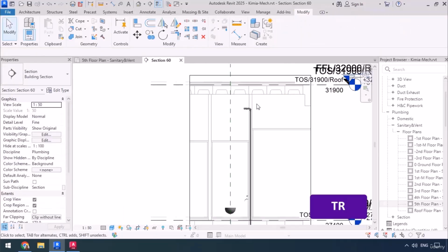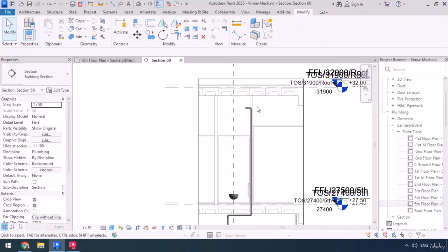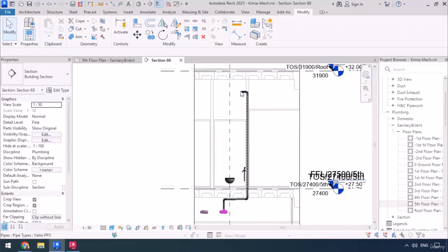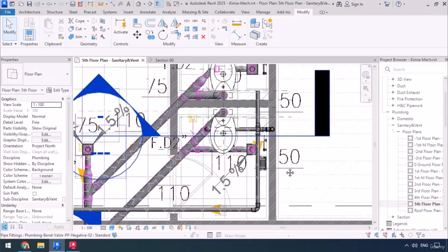So that's why I said that it's best that you start with the lavatory pipes, and by drawing the lavatory's vent pipes, we understood that if we have sanitary pipes down here, then the vent pipes are going to have to be up here. The sanitary pipes were for lavatories, as well as the toilet fixtures. For the lavatories, it was clear enough that the vent pipes need to go up, and if we look at this one, we can tell that we can't draw this pipe straight upwards from here. So the best possible way is going to the nearest wall, then upwards through that wall to get to this vent pipe. So there goes one fixture.